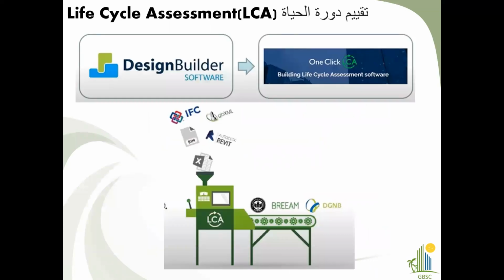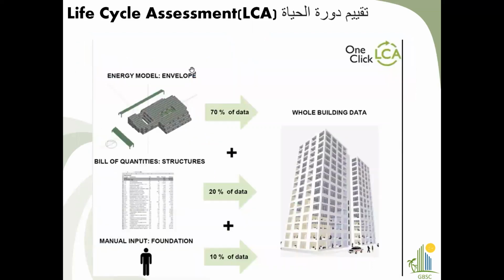For life cycle analysis, it's a very hot term right now. DesignBuilder has an integration with the One Click LCA tool, and whatever information we feed into DesignBuilder basically goes into the One Click LCA tool, and it automates showing whether the design we have proposed, or its carbon footprint, is above the baseline or not. There are certain manual inputs, but most of the inputs, around 90%, the LCA tool takes from the DesignBuilder software itself.